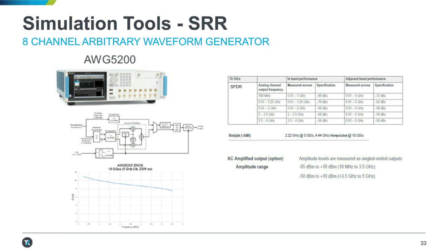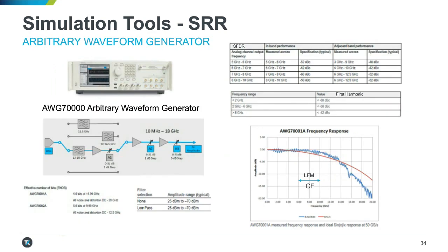It also has a numerically controlled oscillator and an IQ modulator built into the silicon of the instrument. And so we can center these chirps up at different center frequencies without using too much waveform memory. So, a good long-range radar simulation, multi-target simulation device.